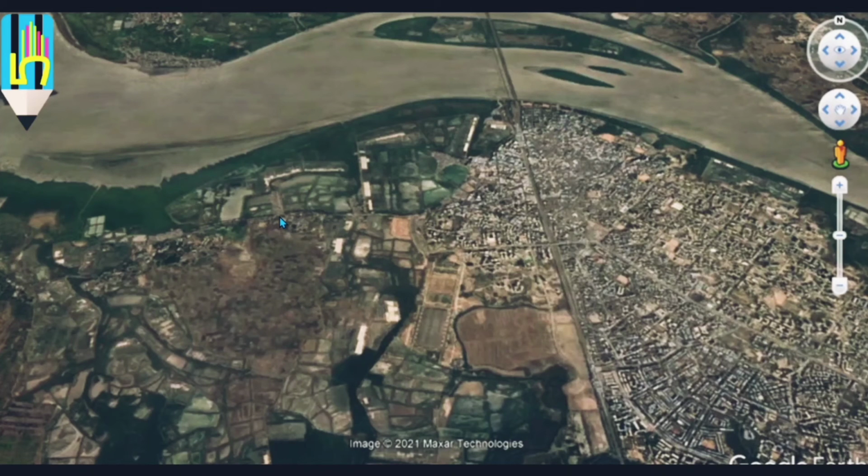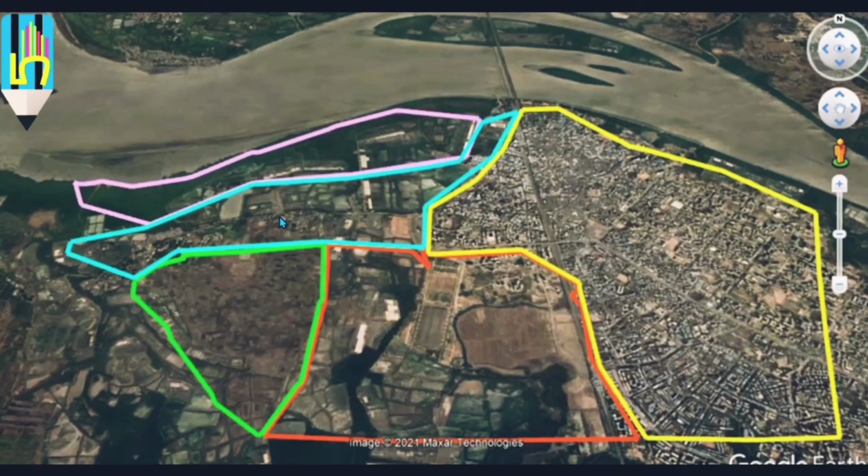Because if we are designing a water supply scheme and we need to do the population forecast, the area in yellow on the right side has very limited potential of growth. So here the method that we can apply is maybe the arithmetic mean method.